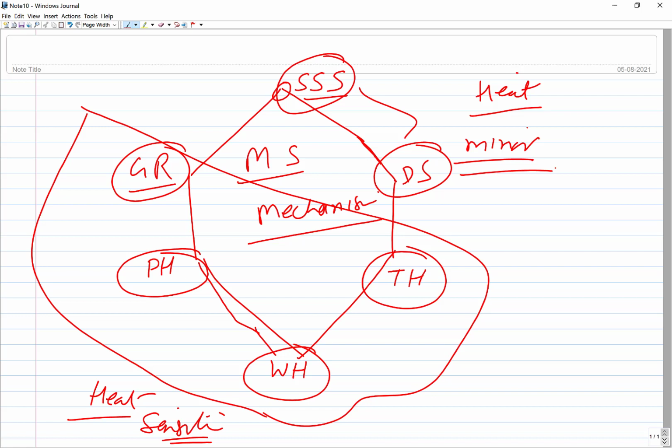Why? Because in metals with dispersion hardening and solid solution strengthening, the strength is imparted by the presence of constituents like alloying elements or reinforcing agents, and it is not expected that application of heat will change things in any way, except that minor grain coarsening can take place. That may not be a significant factor for a metal strengthened by solid solution strengthening or dispersion hardening.